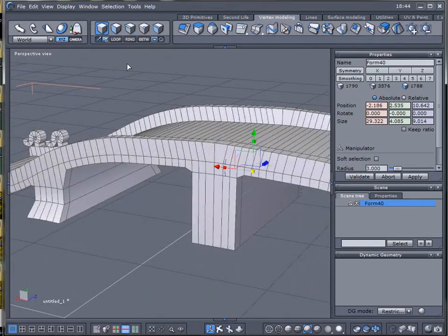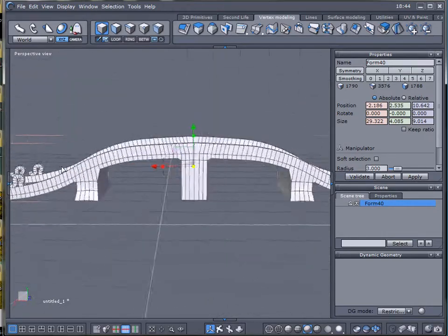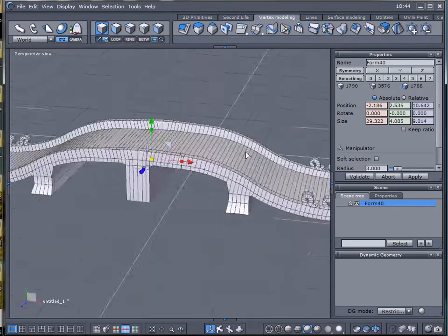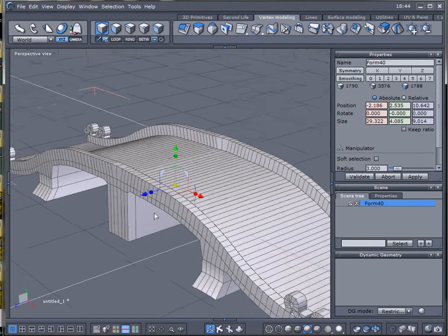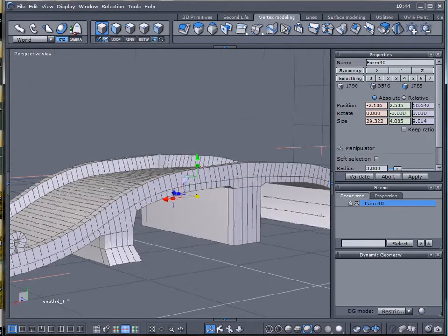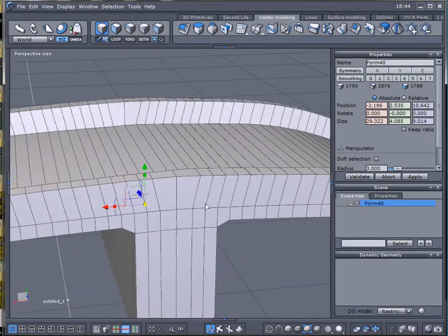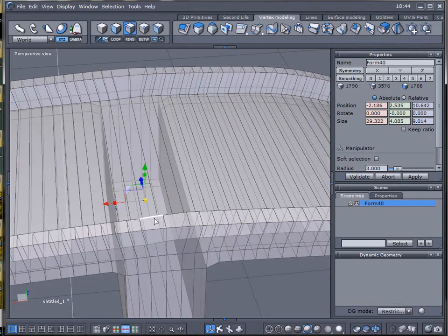Okay, and here's our bridge. We can add more details if you want. But this is a concept, and what we used is a line and surface, and then added thickness. It's one way of creating a bridge, and you can normally spend more time to polish, because I can see maybe right here I don't like those lines, so we need to go right here and add a bit more thickness to these lines.